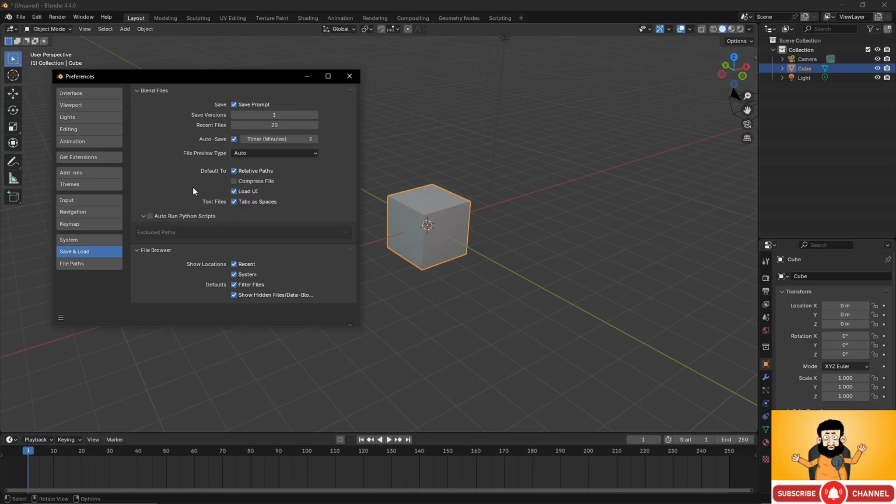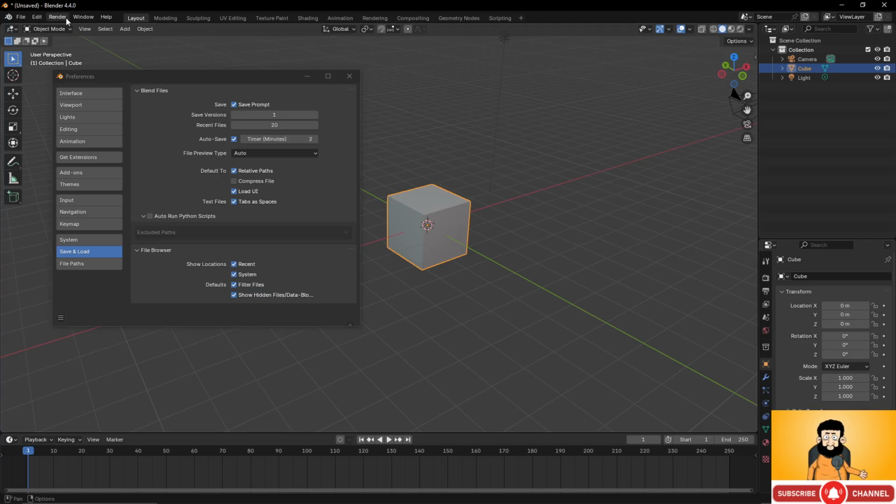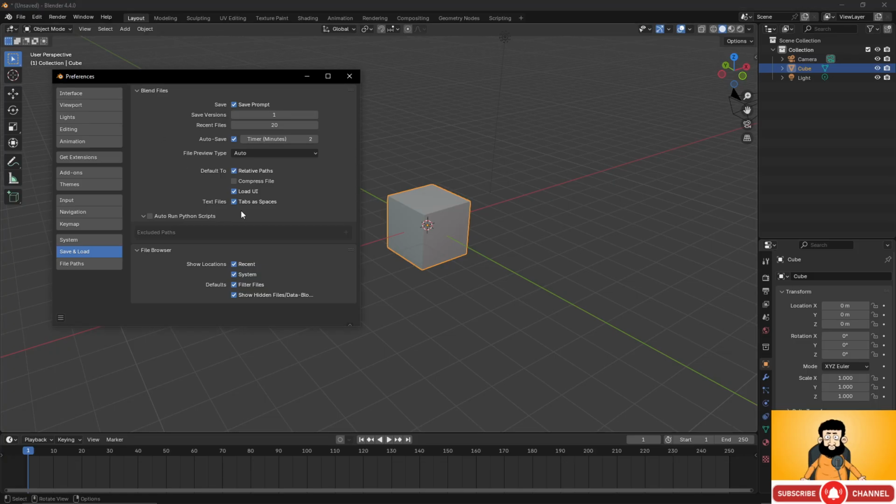Save it somewhere into a folder, and like this it will go into the autosave. If you don't, it can be a little tricky for Blender to manage it well, and you can lose your work. So it's best to save it somewhere by default.